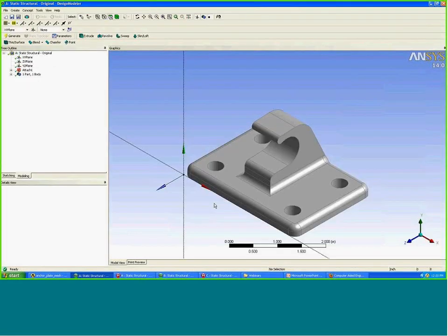So let's look now into Design Modeler. We have this part C in Design Modeler, a big hook part with a base plate, and what we can see is that this is not in its current state ready to be brick meshed. So we can't just sweep it. We'll have to either use one of the advanced algorithms or do some slicing and dicing to create a brick mesh.